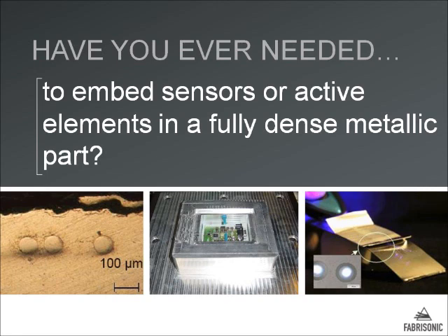We're using this to make a material with a coefficient of thermal expansion of 0. You add the nitinol into the aluminum matrix. As the aluminum heats up, it expands. However, over a specific temperature range, the nitinol, as it heats up, goes through a martensitic phase transformation and actually contracts. By varying the ratio of the two materials, you can make a material that essentially has a coefficient of thermal expansion of 0.